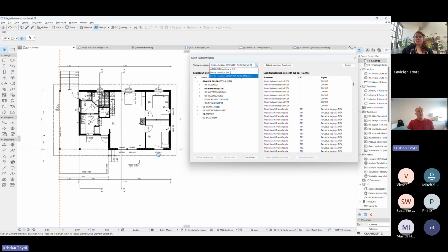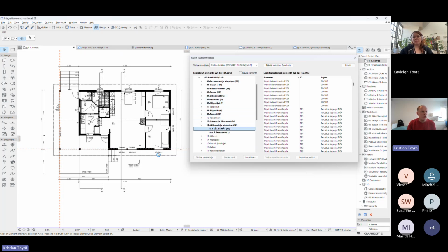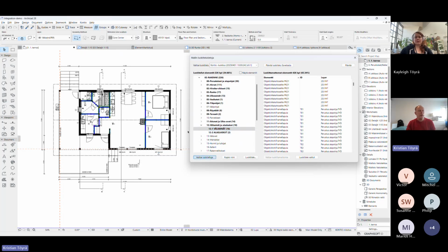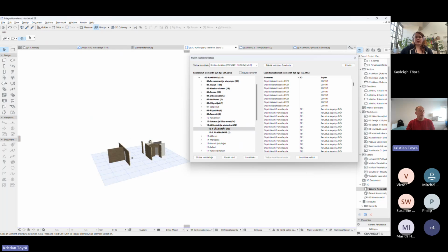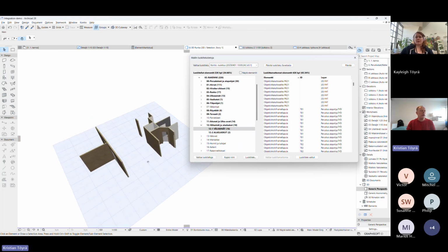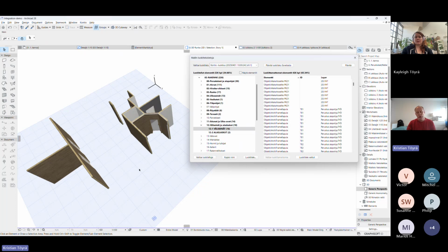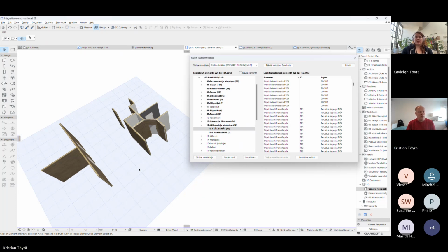Archicad supports many classification systems. So this system is actually downloaded from the Contio ERP. So it's like a class tree. And I've downloaded one, I'm using that one. For example, I can show you that non-supporting walls, small walls, whatever they are, there are 16 of them, and these walls in this house are classified as non-supporting walls, or is there a better word for them?